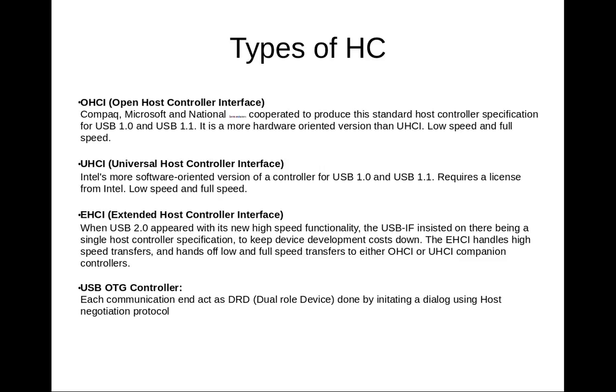So basically there was a concept that devices can be connected to a host, but through USB you cannot connect a host to a host. So it was a major thing. The implementer forum came up with something known as On-The-Go devices. The On-The-Go devices follow a simple rule: either one can be host and the other a device, or the other can be host and device. It's kind of vice versa. If one is host, the other is device, then the other should be host and device.